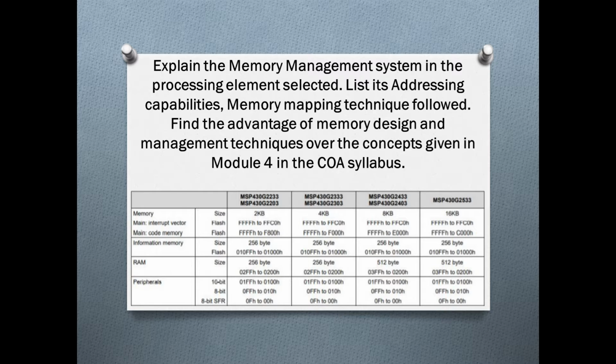The program memory and the data memory can be accessed with byte or word instructions. Part of the peripheral modules are realized as 16-bit wide or 8-bit wide modules. Data in the memory: bytes are located at even or odd addresses. Words are located in the ascending memory locations aligned to even addresses. The low byte is at the even address, followed by the high byte at the next odd address.